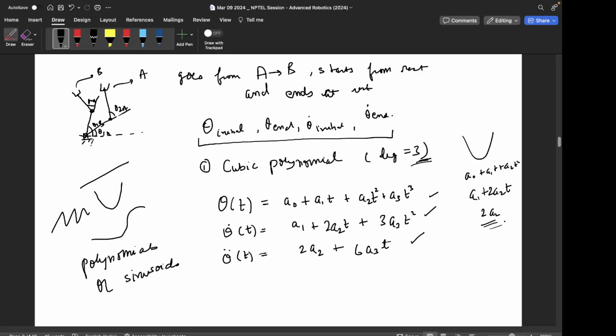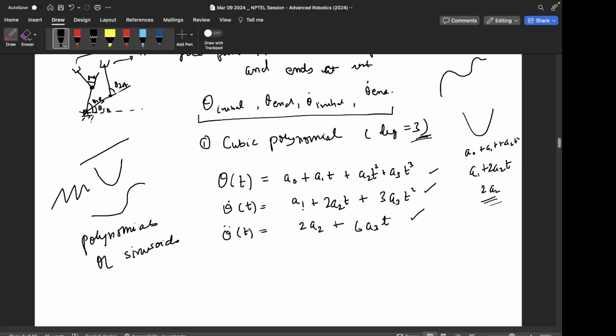This becomes really important when you have obstacles in your environment, or complicated maneuvers, so you can have more curvilinear trajectories. It basically increases the dexterity of the manipulator. But cubic lies in a very sweet spot. It gives this freedom also, and it has only four unknown variables, so the number of unknowns is manageable.